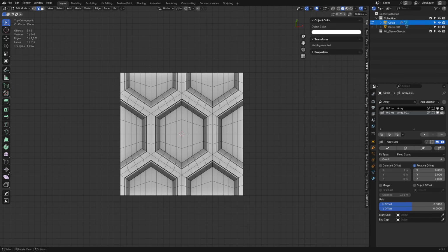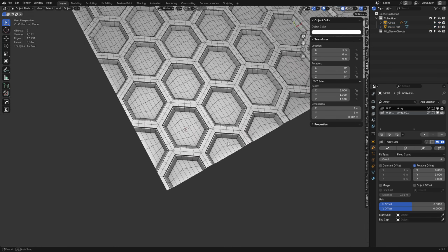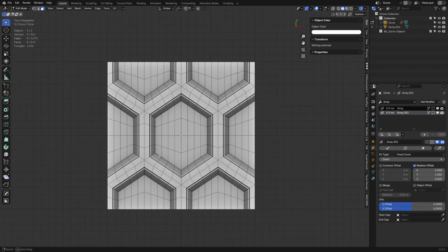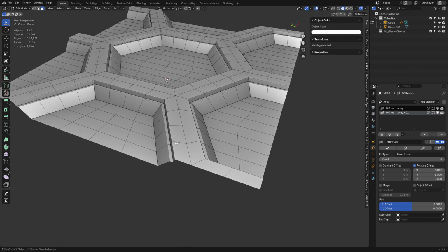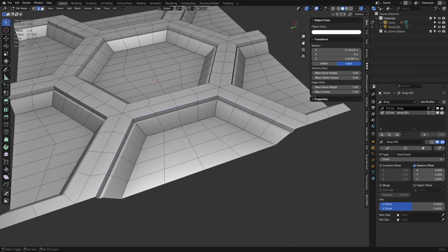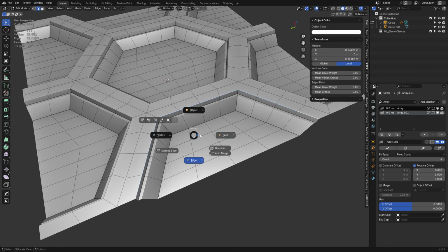Something along these lines. You just want to pay particular attention to all these little nuanced problems and make sure you're doing the right thing. For example, if we try going around and beveling certain edges now, some of them will work fine. Other ones will start to bevel really badly. Maybe not in this particular case, but you do have to be aware of those kinds of things. It happens. Some of them you'll be able to get away with beveling, some of them you won't.